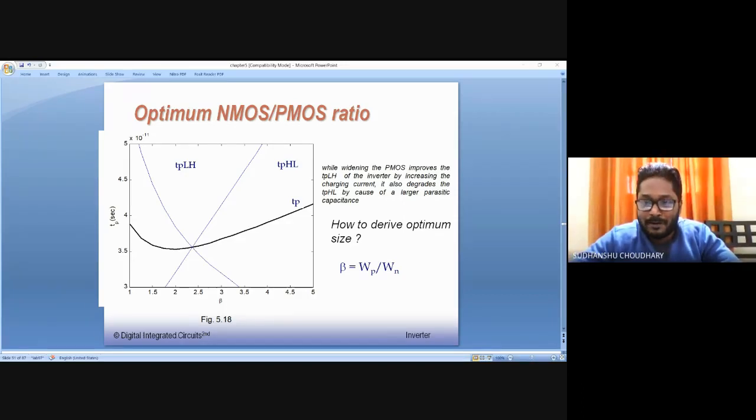So for low power applications this can be used. That is the sub-threshold region of operation. But still, we are not sure what the actual value of the current levels will be when the actual fabricated circuit comes up in our hands, right? So it is undesirable.